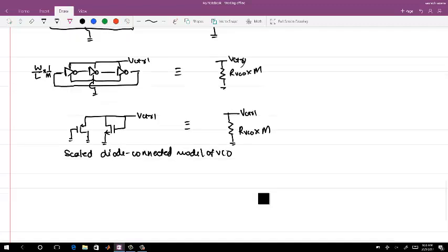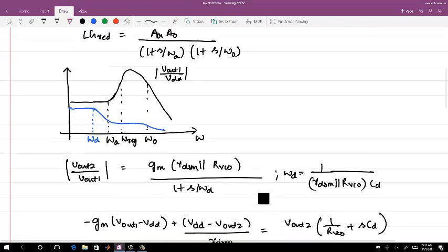One other thing: if you are spending more power in the case of the actual regulator, the only thing you can do is move this to a larger bandwidth, whereas your PLL bandwidth is still down. PLL bandwidth is still sitting somewhere here, and you move the frequency to the right-hand side by spending more power in the regulator. But it depends how much you move, so you may still have the peaking.